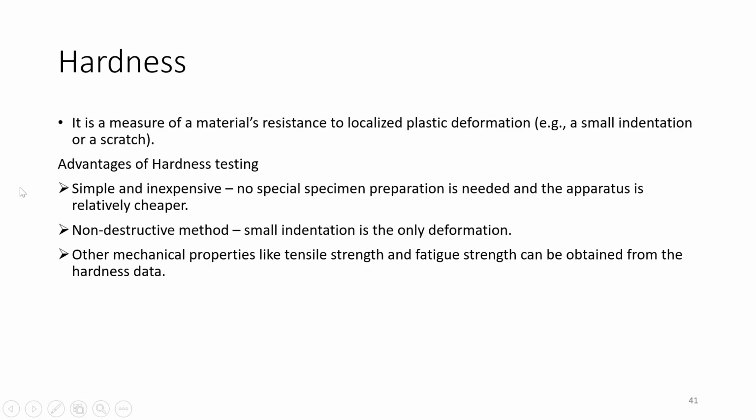This is a simple and inexpensive technique, and it requires no special specimen preparation, which is needed in the case of other techniques such as tensile testing or fatigue testing. The apparatus used is also relatively cheaper compared to other testing machines, and it is also a non-destructive method. There will be only the formation of a small indentation in the case of hardness.